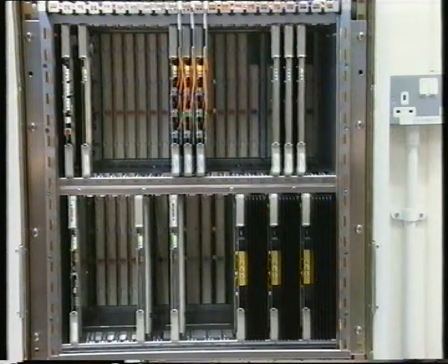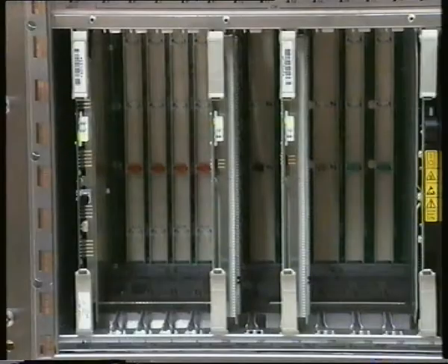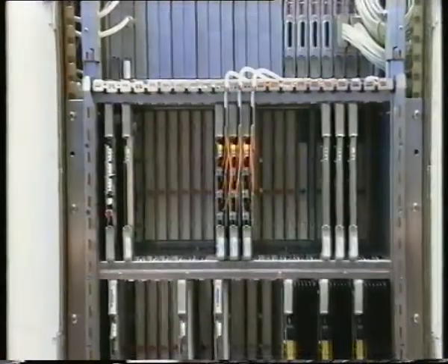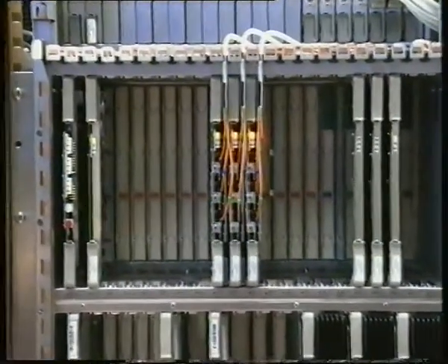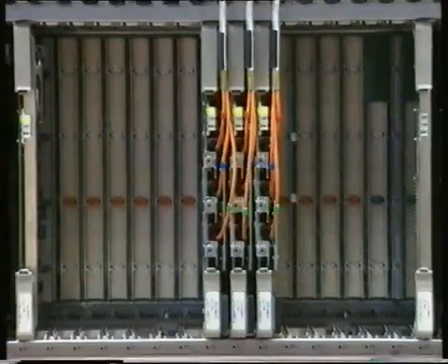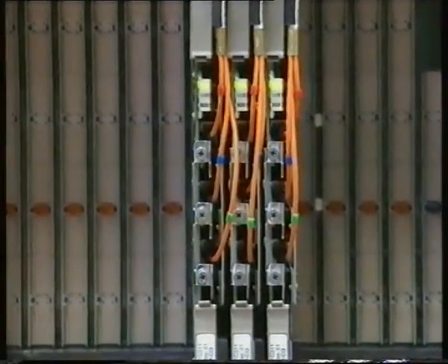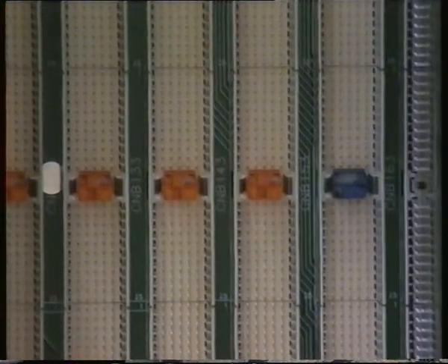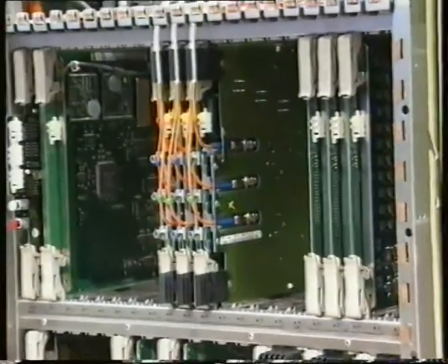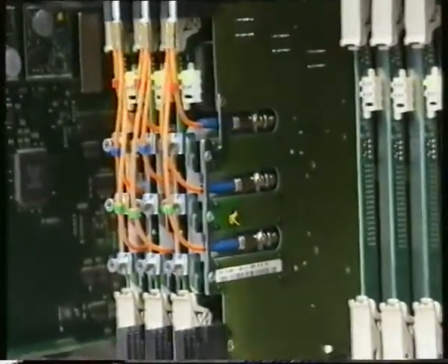The lower two shelves of the sub-rack contain the plug-in units. Here you'll find the common cards required to provide control and switching functions, and the line terminating equipment cards, which are provided reactively and selected depending on the type of access link to the customer. All these cards have a mechanical key to prevent cards being inserted into the wrong slot. Note that any optical connections are made on the plug-in units.